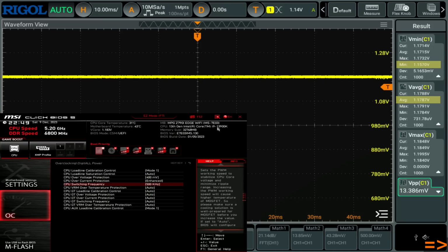The other thing is this is an ITX board that struggles with VRM cooling because there's just not enough space for a proper heatsink. It's a very nice VRM using top-of-the-line parts, and they squeezed about as many phases onto the board as you can, but that doesn't change the fact that you can't have that big a heatsink, and the 13900K is a very, very thirsty CPU.